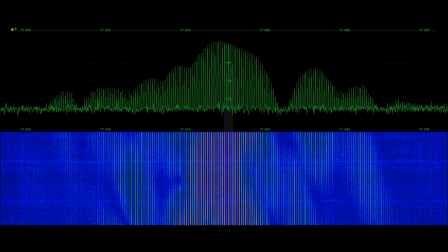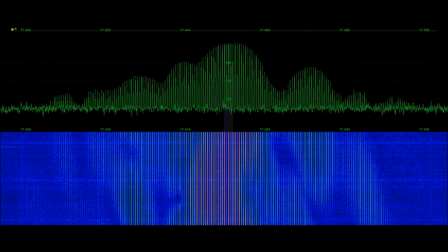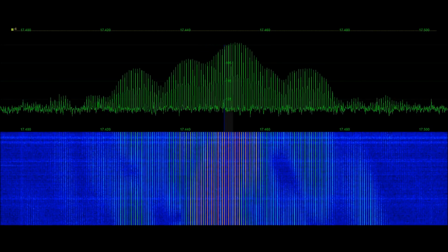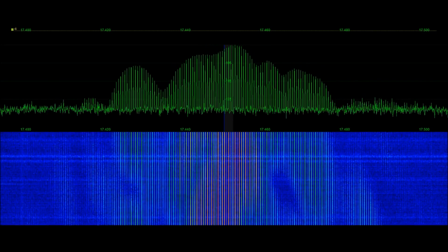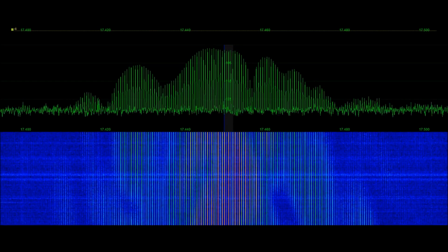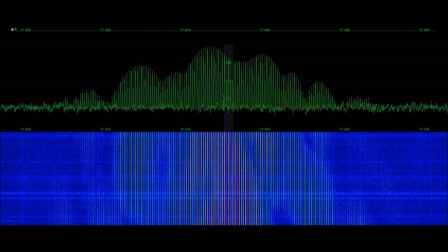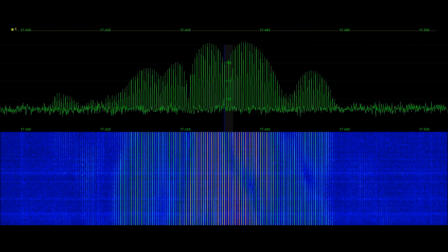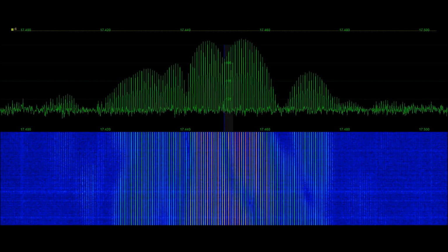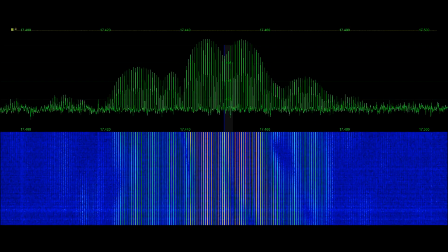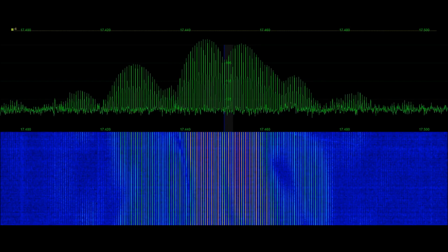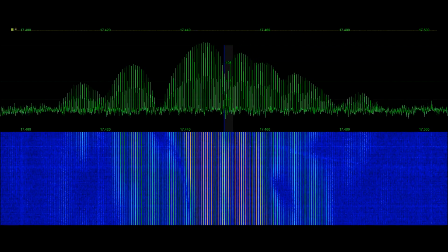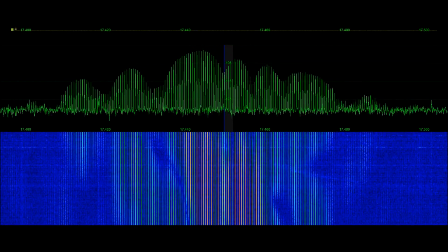Okay, I wanted to grab a sample of this particular signal and talk about what it is, how it's developed, and how it differs from some other signals that we've also taken videos of. So what exactly is this that we're viewing? Well, this is a form of a frequency domain radar. In this case, it's an HF Doppler radar, or continuous or carrier wave type radar signature.